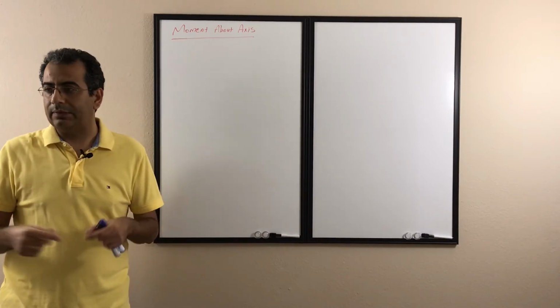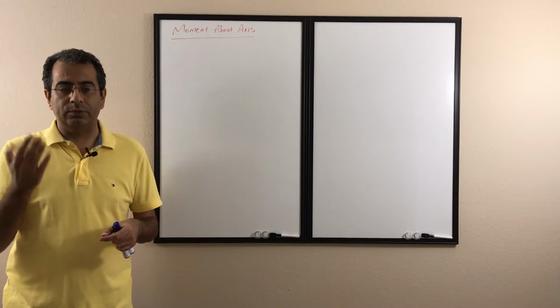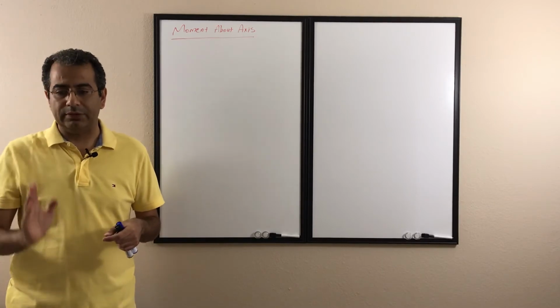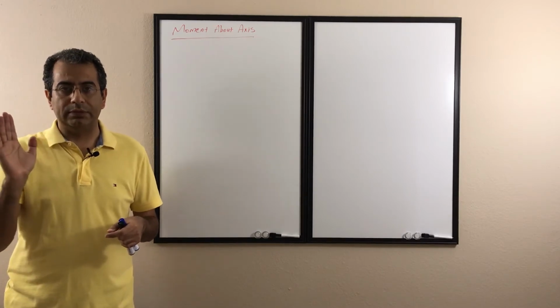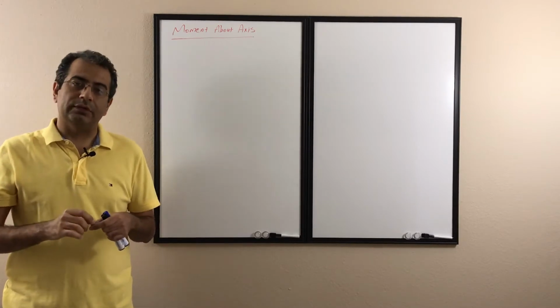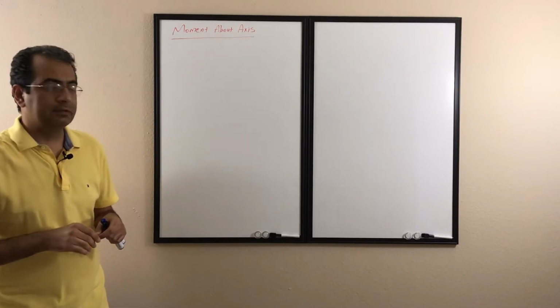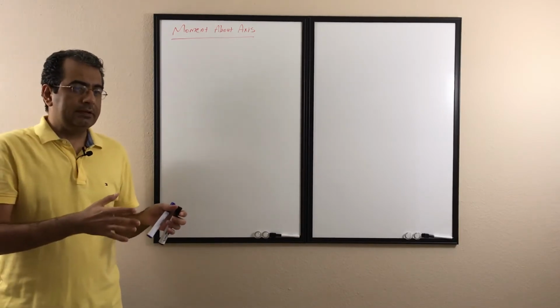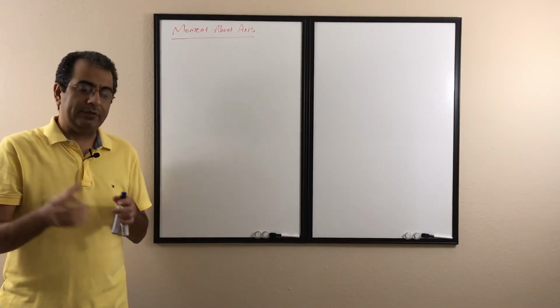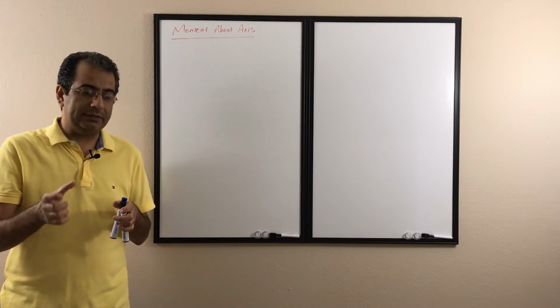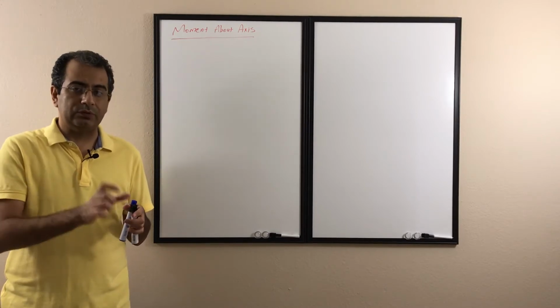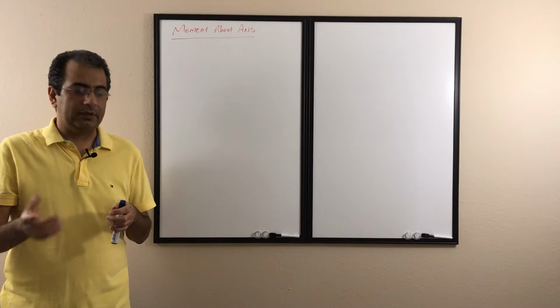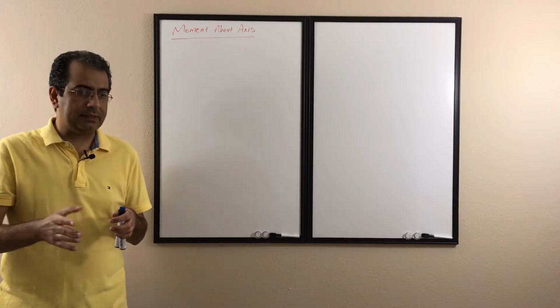The other example is when a door closes and opens. You have the hinge, the axis of the hinge, and want to see the moment about that axis of the hinge. What's the moment about that axis? The easiest way is, if we have the normal distance from the force to the axis, we just do force times the normal distance. It's the same thing.